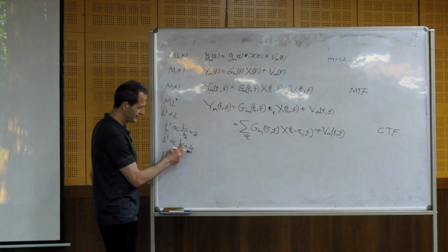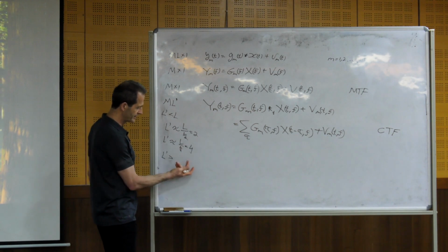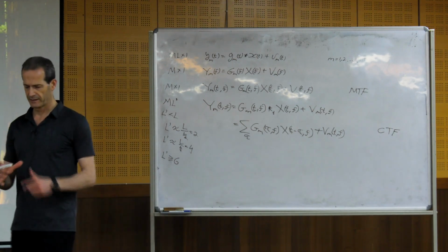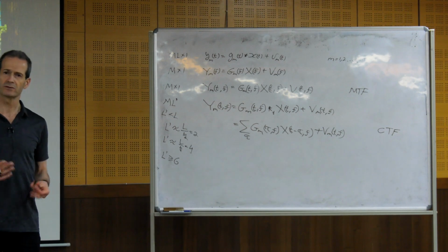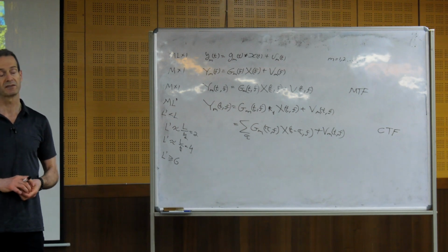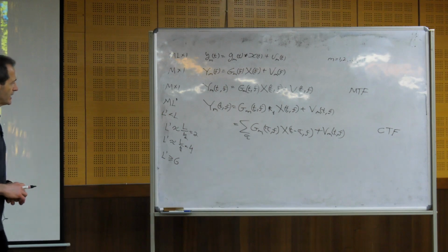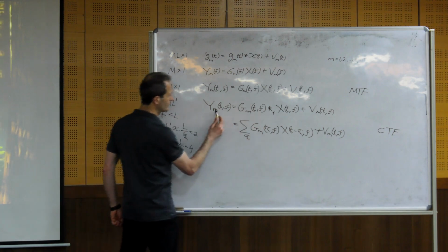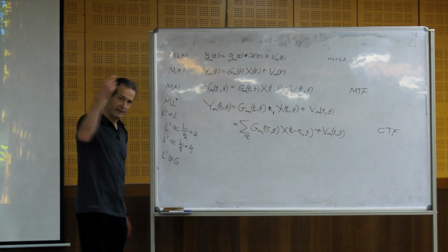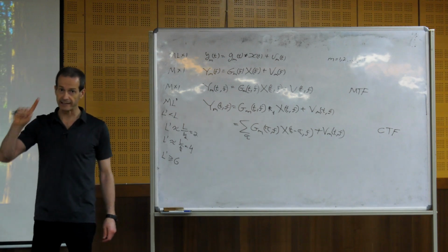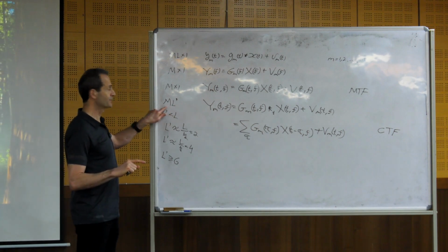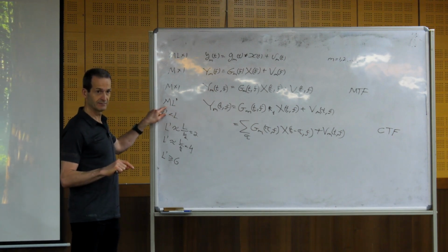If the overlap between windows in the STFT is 75%, which is a common practice, along with 50%, we take like 6 windows here. So the length of the vector of measurements that we process is about 6 multiplied with M, the number of sensors.